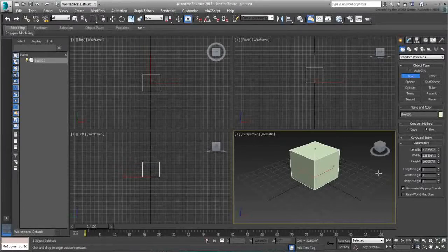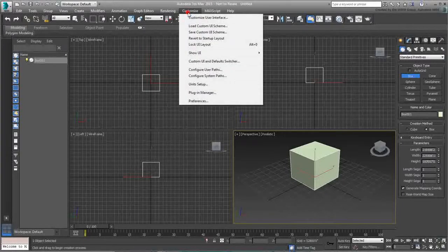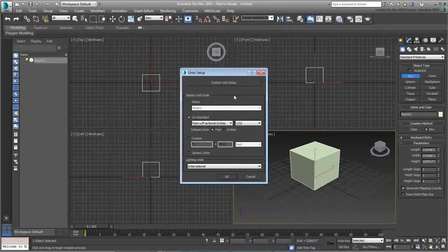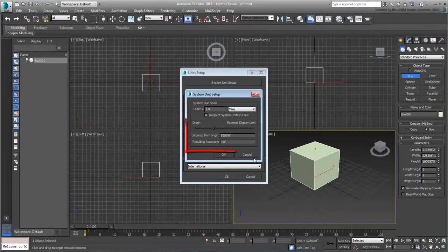Another thing to look out for is the placement of objects in a scene. Typically, when you are creating objects in 3ds Max, you create them around the center of the world. This is the way it should be, as creating or moving objects too far from 0, 0, 0 tends to result in various problems. The further you are from the center of the world, the less accuracy you have. In fact, the system units dialog has a slider that calculates the accuracy loss when moving away from the origin.